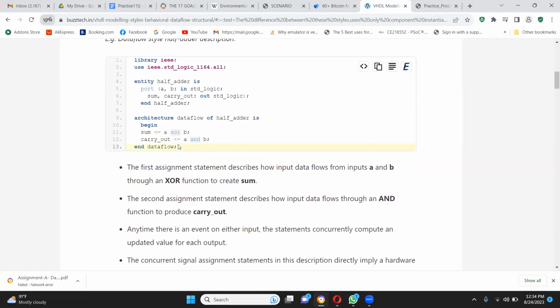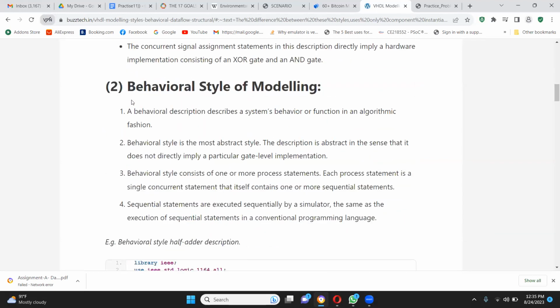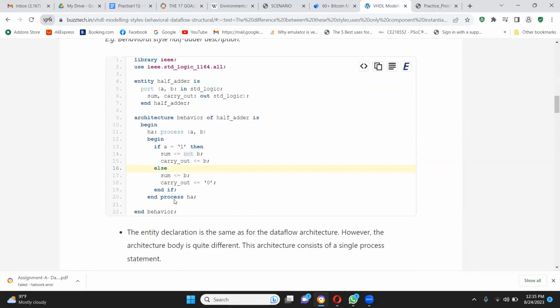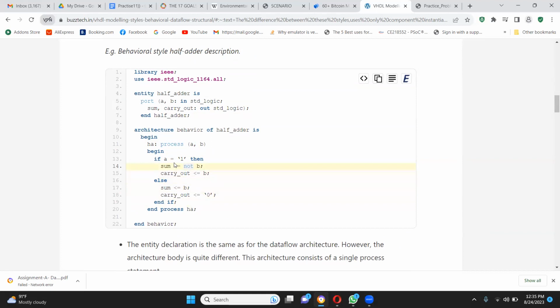I mean, in designing a half adder, here you are not using any XOR gate or NOT gate. You have a Boolean expression for sum and an expression for the carry out. You try to implement these expressions with the help of the assignment operator or the not operator and get the job done. That's what you're trying to do here.